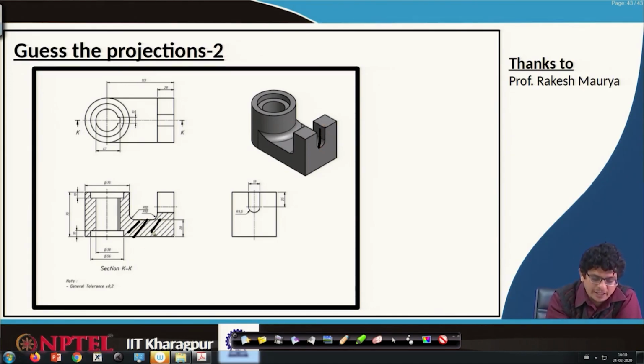So, we will have material element there. This is what we call hashing in these drawings, indicates that these are the cut section. Why we have this cut sections is to visualize complicated internal parts. For example, if it is straight away visualizing it, what we will be having is only this part. We do not know whether there is something like scooping out inside of that material or not. To have that kind of more information, usually people have that cut. So, that indicates that there is something like this kind of cut what we are going to have.